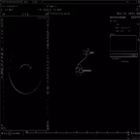For example, I can state add P is add P plus a vector, let's say 0, 0.1, 0, and that will push up my entire torus by 0.1. That is coding. A lot of visual people, though, don't like coding too much. And that is why Houdini introduced a different way of coding called VOPs, VEX operators.